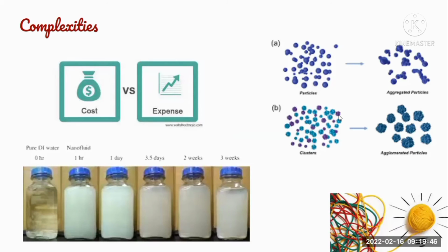Let us see the complexities in the preparation as well as the employment of these nanofluids. Preparing these nanofluids is costlier because of the time in preparation, the special ambience under which the powders or the fluid are prepared, the raw materials being used, the energy used for synthesis, and the volume of nanofluid prepared during the synthesis procedure is very small at that cost. So the outcome to cost ratio is going to be very low.